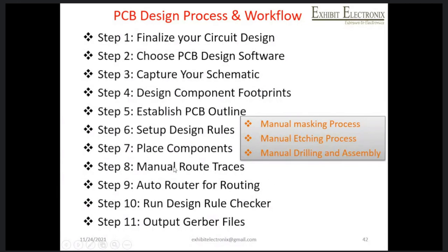Routing process is very important. So there are certain design rule checks, because you are not going to print it, you are feeding it into a machine, and the machine should understand whatever schematic you route here, otherwise it won't give the output. A proper design rule should be there. We have to check it before feeding into a machine.